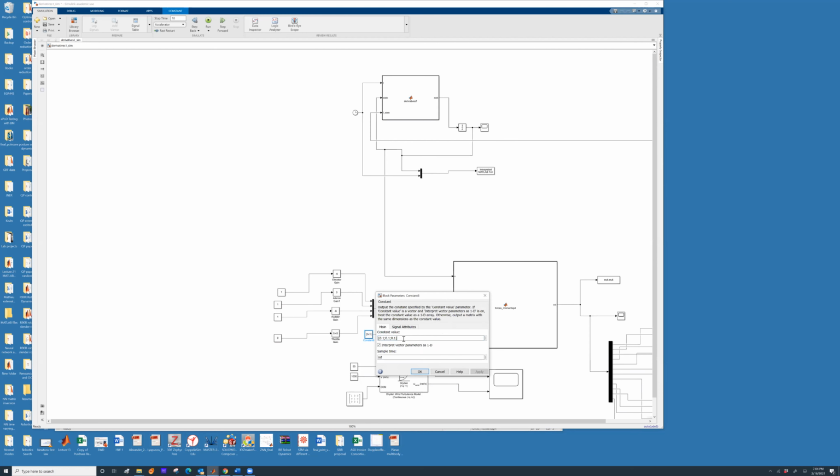So you will have to substitute the appropriate wind value to come up with a realistic simulation. This indicates that the wind velocity is very, very small. That may not be the case. Now, this is the constant part of the wind, and you have the gust part of the wind. That comes from this Dryden model.